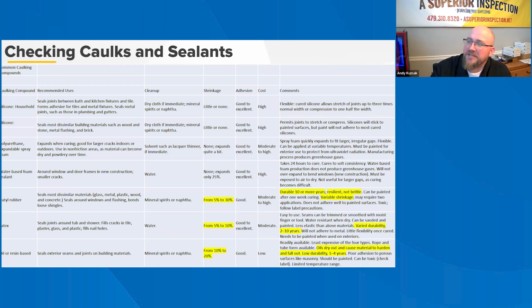Standard quality caulk and application practices, combined with shrinkage and swelling of the building's components, usually result in the onset of gradual failure of the watertight seal within a few years. Caulking can prevent water damage inside and outside of the home when applied around faucets, ceiling fixtures, water pipes, drains, bathtubs, and other plumbing fixtures. Caulking can also be used to seal air leakage. Some general information regarding the types of caulks and sealants is provided in the table, including longevity, the best uses, and the appropriate types of joints for given sealants.